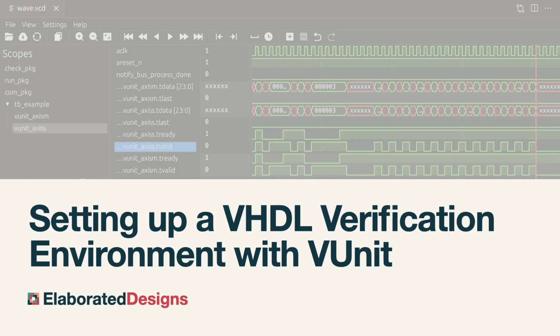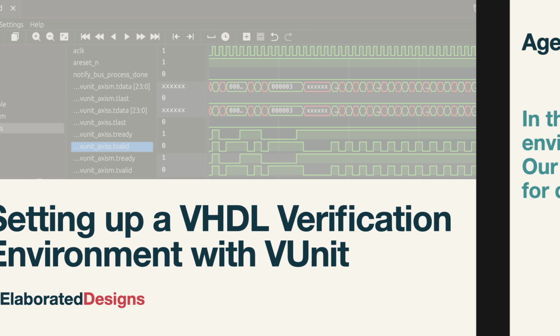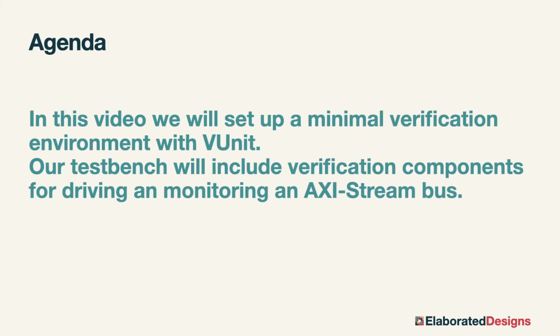Using a verification framework can dramatically improve the quality of our designs. However, setting up a verification framework from scratch can be quite daunting. Luckily, there are open-source libraries that handle most of the infrastructure required for creating, running, and managing our tests, so that we can focus on the parts of our test bench that are unique to our design and add value to our development process. In this video, we will set up a minimal verification environment with VUnit.